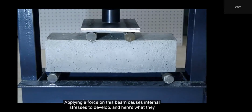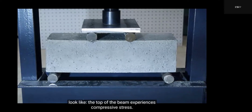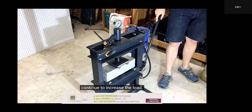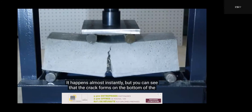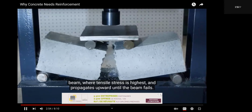Applying a force on this beam causes internal stresses to develop, and here's what they look like. The top of the beam experiences compressive stress, and the bottom of the beam experiences tensile stress. You can probably guess where the failure is going to occur on this concrete beam as I continue to increase the load. It happens almost instantly, but you can see that the crack forms on the bottom of the beam where tensile stress is highest and propagates upward until the beam fails.